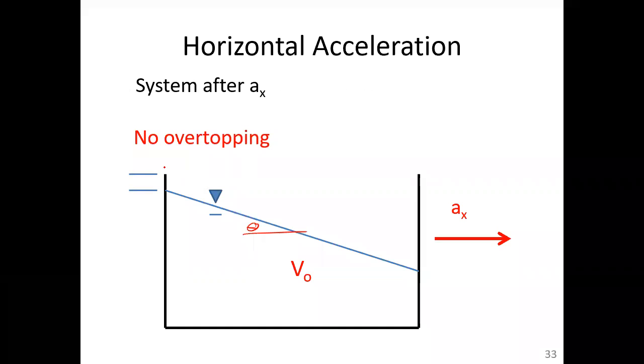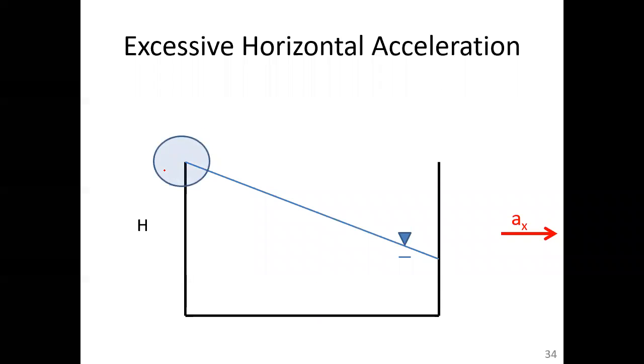And so this point then becomes a fixed location from which the tangent of theta or the slope occurs. So you could actually keep increasing ax, and now you've lost fluid, and you can keep increasing ax such that you're losing more fluid, and now the slope is actually riding along the bottom.